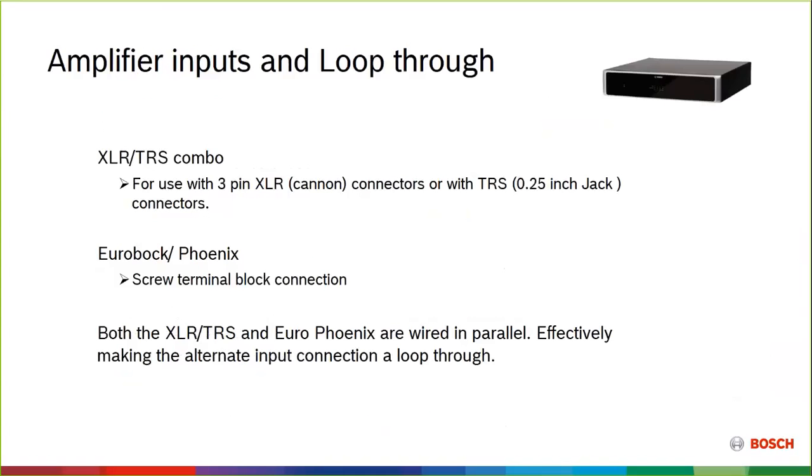Amplifier inputs and loop through. Like I said, it's XLR. It's 4 XLR TRS combos and a Euro block, so we kind of give you the options. And those are wired in parallel, so it's one or the other. It's not 4 Euro block and 4 TRS. You don't want to put 8, or you're just bolting those together and we'd overload them.